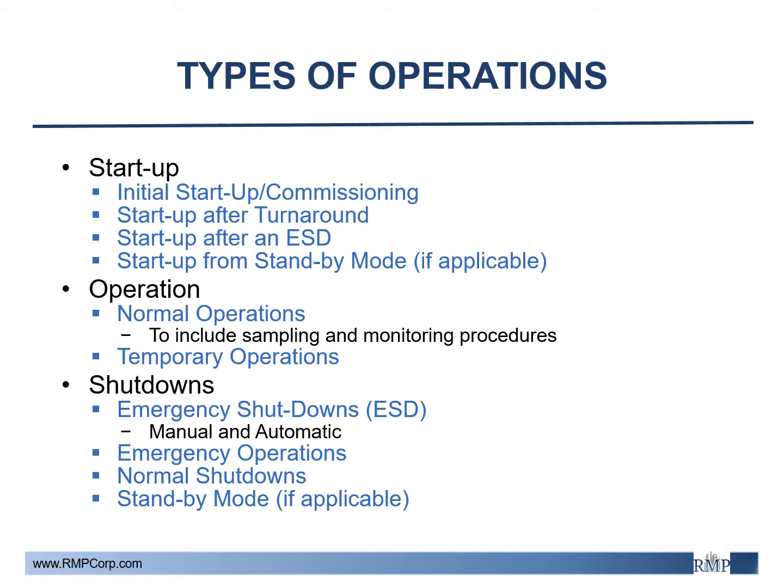There are some operations that are not typically utilized. However, your system should be thoroughly examined if these needed to be included in your SOP. Initial startup and commissioning procedures are warranted when this is the first startup of this process or the piece of equipment. A hint to whether or not this may be applicable is whether there are additional cleaning, purging, or flushing that is required per your provided operations manual or as dictated by the equipment manufacturer prior to startup. The procedures for these steps may be minuscule and might only be used once, but these must be included in your SOP.